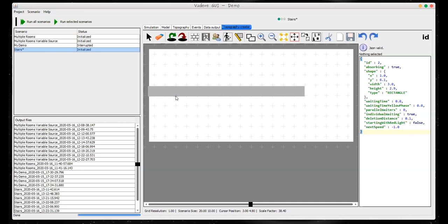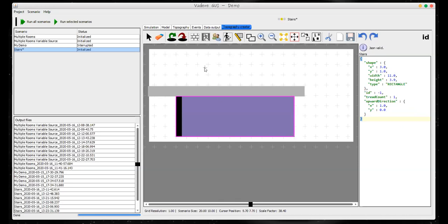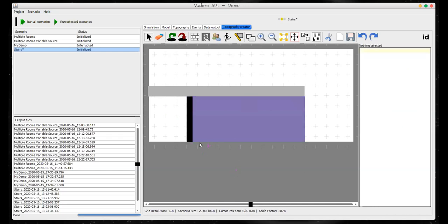So let me show you how this works then. If I want to create a flight of stairs that is roughly 10 feet, again assuming my grid is 1 foot per grid, so that's 1, 2, 3, 4, 5, 6, 7, 8, 9, 10 stairs. Actually, let me make it 11 feet, and there's a reason for that. Let me move this down to the bottom of the stairwell so that it's right next to the wall. I'm going to extend this all the way down to the bottom just so that I don't have simulants trying to run through that empty space.